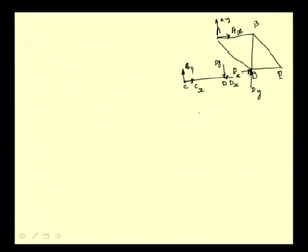So, what are the unknowns? We have AX, AY, dx, dy from this free body diagram, and Cx, Cy from this free body diagram, because this dx and dy are equal in magnitude and only opposite in direction to these two forces.